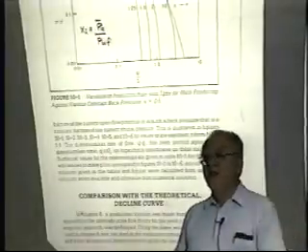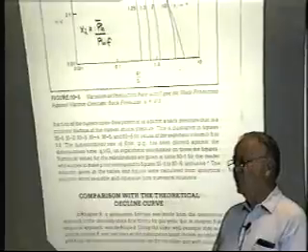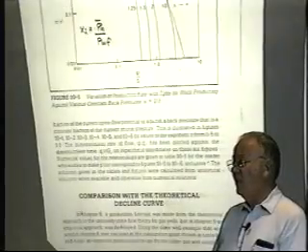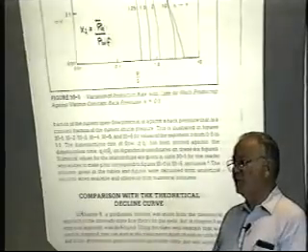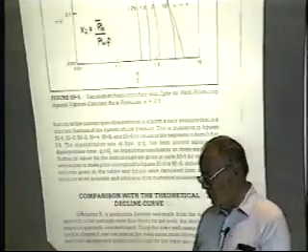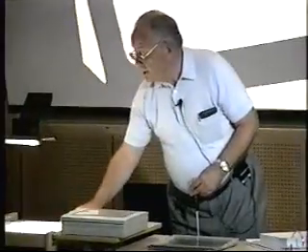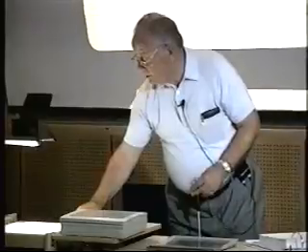When you're in decline, the objective should be to lower your bottom hole flowing pressure to the lowest value possible as early as possible to recover the maximum amount of reserves. That should be obvious, I hope. This is nothing more than the tables. I'm not going to go through them individually.